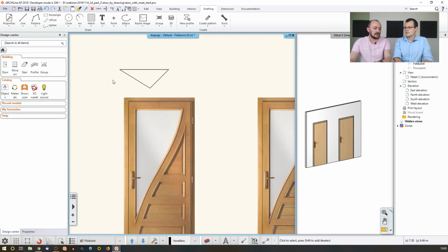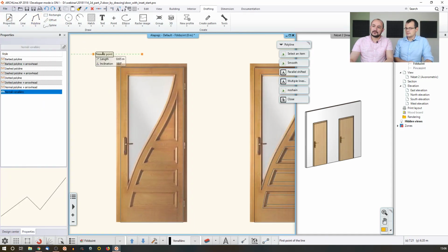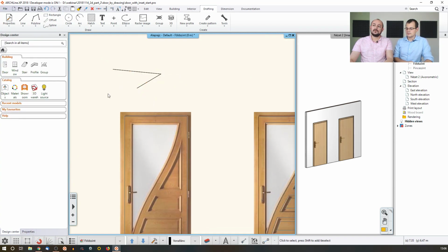It's kind of similar to using a slab, for example. It always has a closed contour. Yes, you cannot create an open contour for a slab from the top view. But if I use the polyline and I just do the same, it just stops there. So if you tend to create something that is an open profile, I will cover that later.